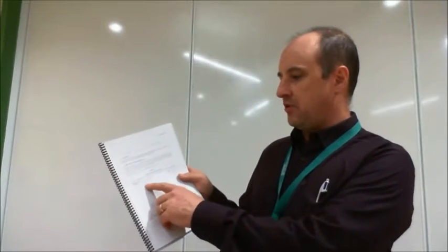Okay. What you have to do is select the return period. So there's a table here, 3.1. V1 is the speed that the wind is going to reach roughly every year. So in region A, 30 meters per second. Down to the wind speed that is going to come along roughly every 10,000 years, which is quite a lot higher, 51. Mostly, for most buildings, you're talking about a 500-year return period for your design wind loads. And these are ultimate loads. For serviceability, for deflection, you're talking about a lot less frequent.